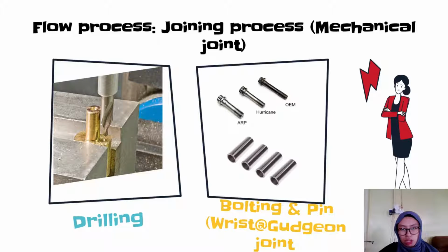We need to drill a hole in both sides of the connecting rod to join it with the bolt and nut. Firstly, we need to make a center drilling for the big end bolts by using a 10 mm drill tool. After that, we drill both sides of the bolt holes using a 3 mm size.